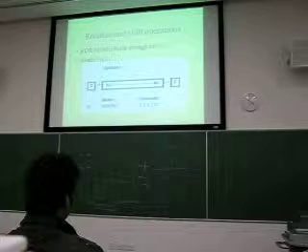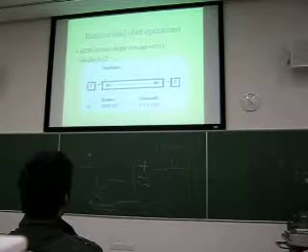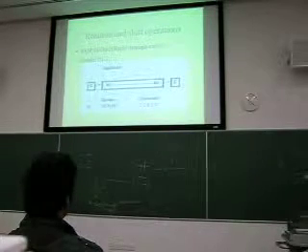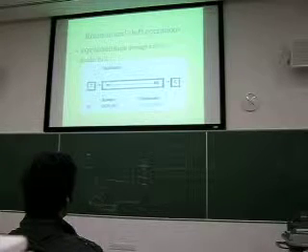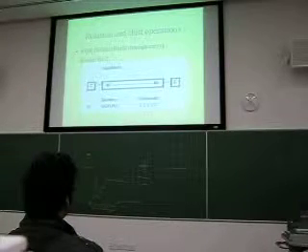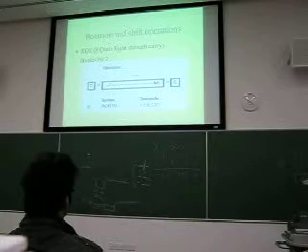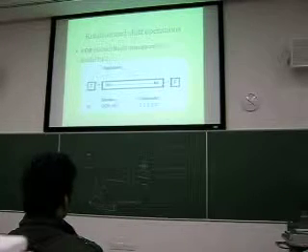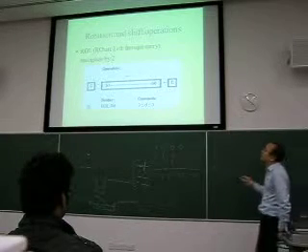Yes, it's the status register. Okay? So that flag gets shifted to the right, whereas the least significant bit gets loaded into the carry bit. So it has the effect of division by 2, because this is the most significant, this is the least significant, and you're shifting them.